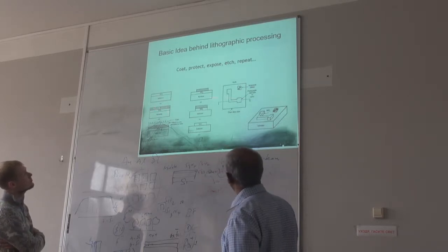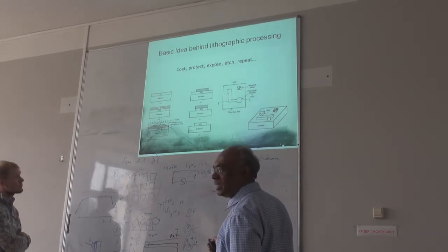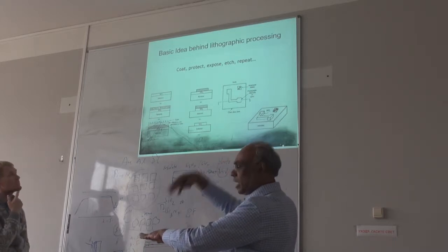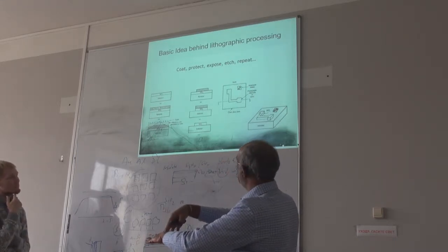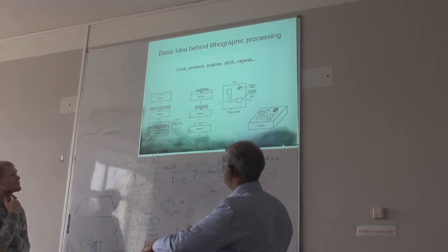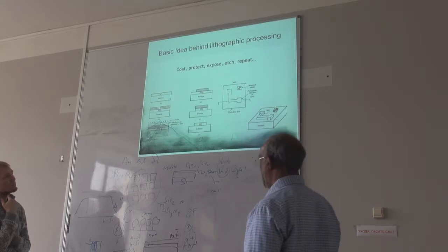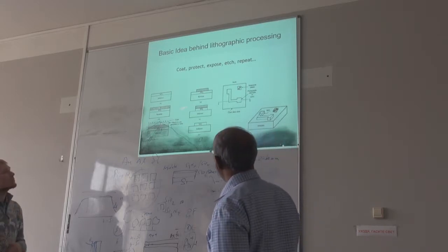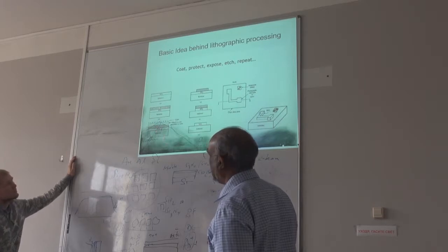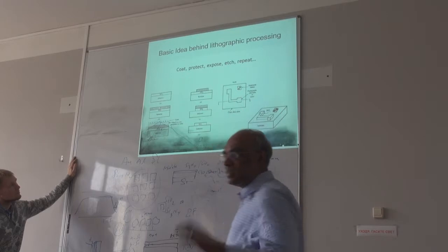Now you take this mask and put it here. You just put it here, that has that pattern, right? You just expose to light. In this case, photolithography, we just expose to light. So if you use UV light, then this part is exposed to that light, right? So not this part, only this is the hole here.